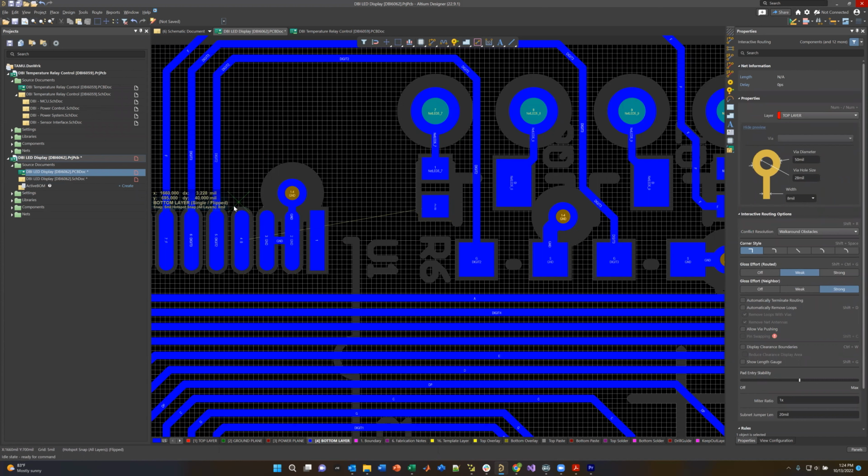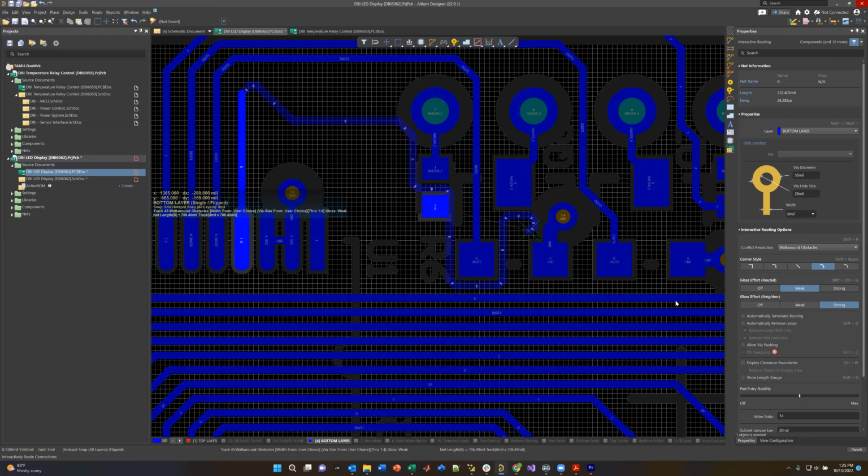And of course, notice it won't let me route anywhere that, it tries. It's hugging and moving around because it's not going to let me intentionally short the trace. So let's go ahead and route it up like this. And I'm going to just show this, and I'm going to go back to the way it was in a second. So that is a hand routed connection.